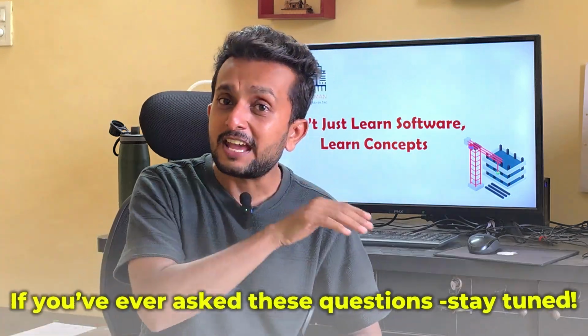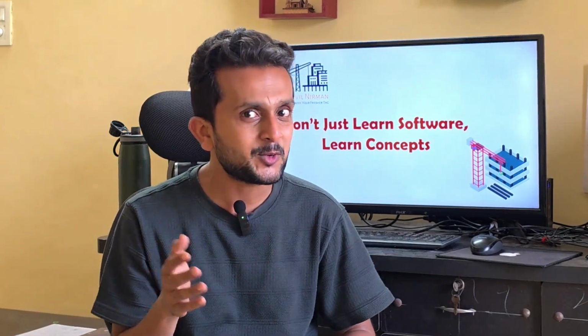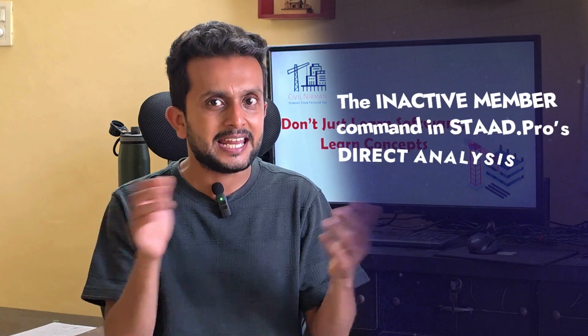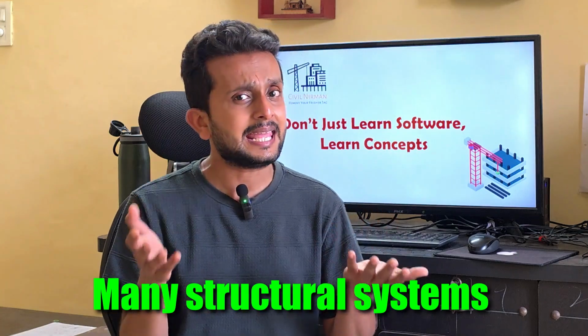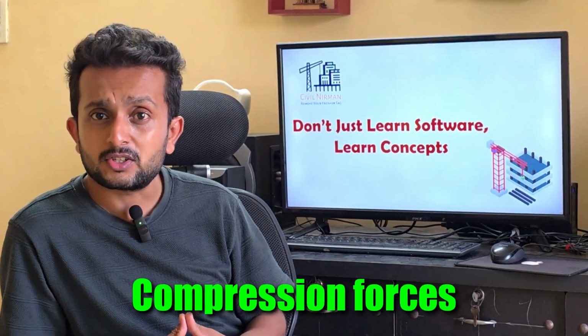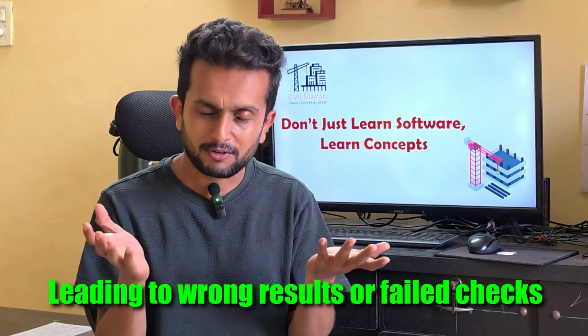If you have ever asked this question, stay tuned, because today I am going to show you a super powerful yet beginner friendly feature, the inactive member command in STAAD.Pro's direct analysis. Many structural systems like X bracing have members that work only in tension, but if you don't model them carefully, they may show compression forces under gravity loads, leading to wrong results or failed checks.